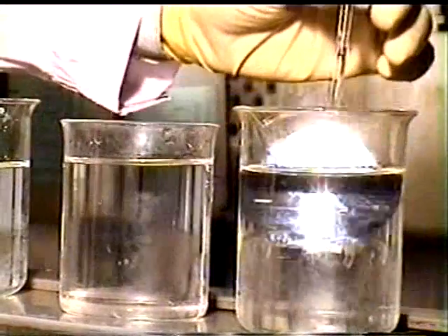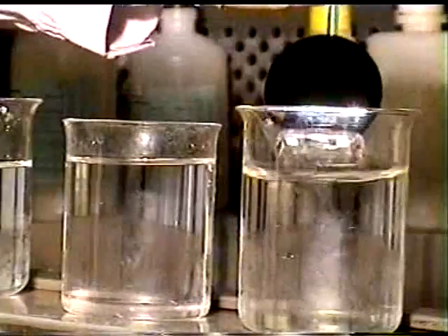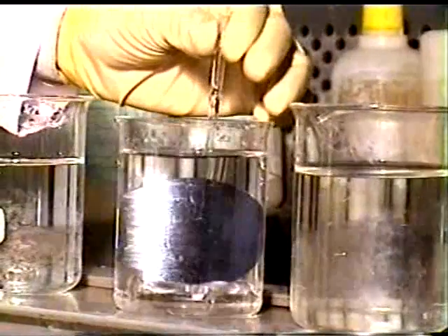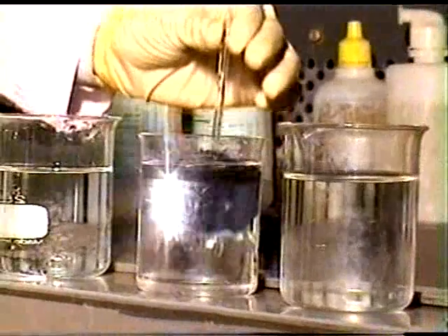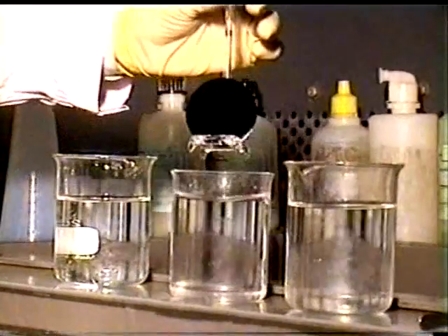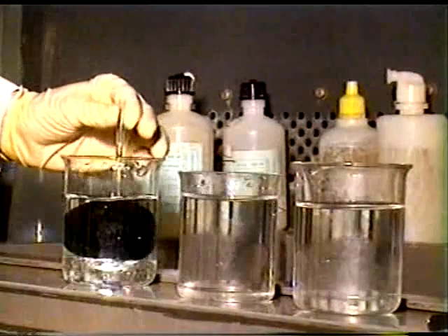The wafer is now taken out and dipped in DI water for rinsing. Please notice that the wafer is being dipped in a series of beakers containing DI water. Subsequently, this wafer would be taken out and dried in a spin dryer.